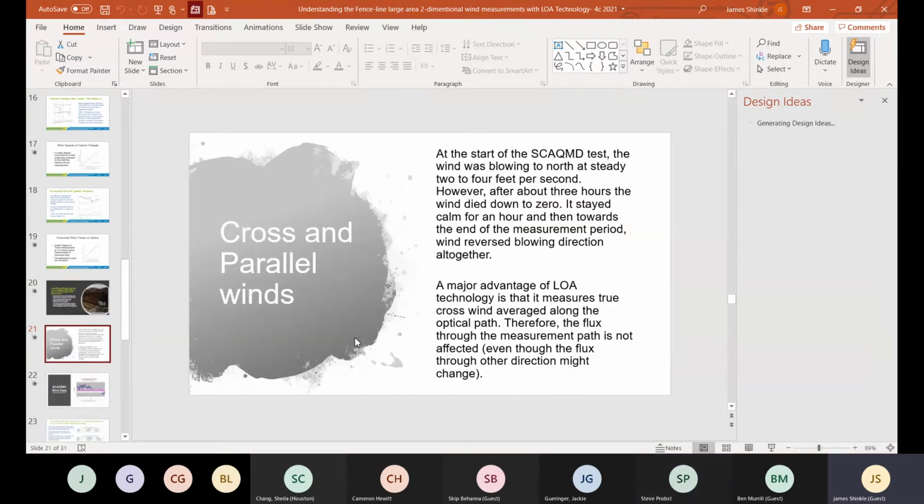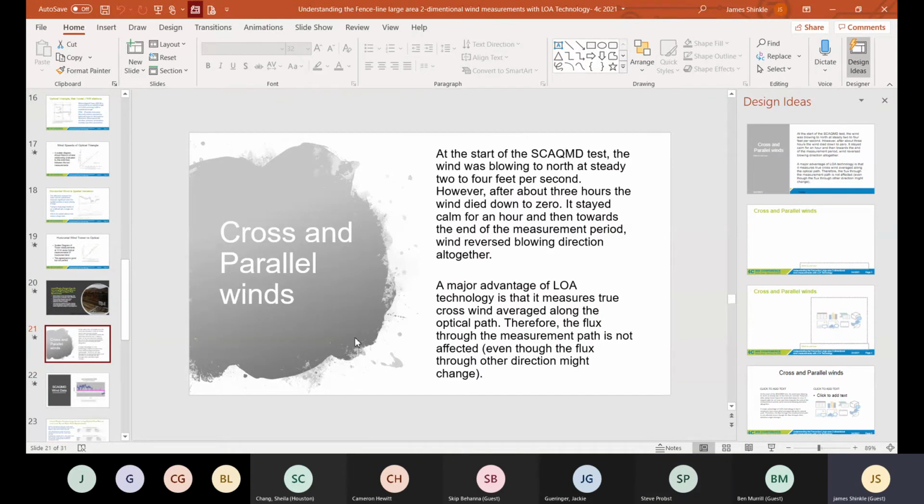And I've always felt that it validates open path gas sensors, because when you use an open path gas sensor and you're getting the concentration of gas across that whole plane, you might as well get the wind across that whole plane too. Yeah, if you pair this with fence line monitoring, like an FTIR type fence line monitoring, then you could get a much more accurate quantification across the fence line. Right. You could look at the mass emissions across that whole spatial area.